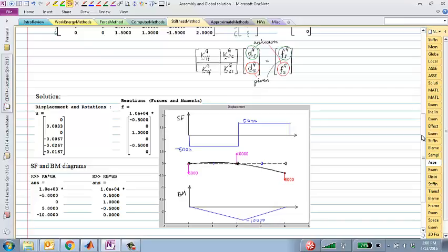How would you find the change in length of the element? If you already have the displacements of all the nodes, you use that to find the change in length of the element for the truss by picking out the degrees of freedom for that truss element. Let's say if I have 10 nodes and one truss element is connected to nodes 2 and 5, then you would pick out those 4 degrees of freedom from the global displacement vector.